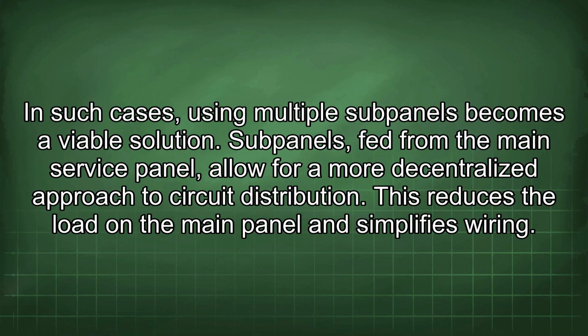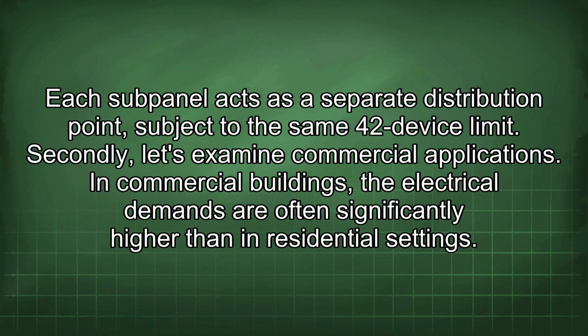Subpanels, fed from the main service panel, allow for a more decentralized approach to circuit distribution. This reduces the load in the main panel and simplifies wiring. Each subpanel acts as a separate distribution point, subject to the same 42 device limit.